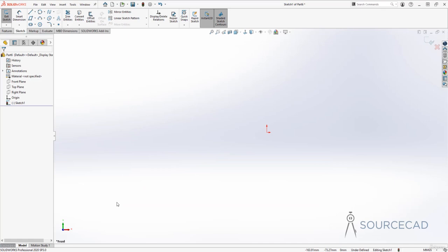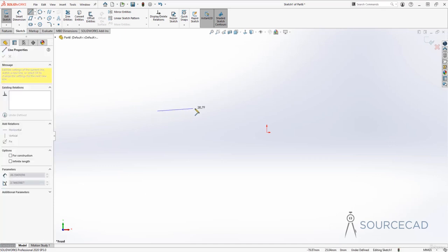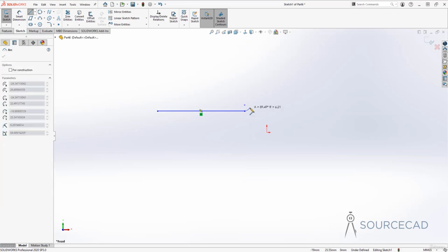Now finally, you can convert your line tool into arc very easily, kind of like this. So I'll start the line tool, I'll click at a point and I'll make a simple horizontal line. Now again, it will start the line obviously, but if you want to convert it into arc, all you need to do is go back to the same point, but don't click, just go back to this point and now move it out again. And this time what we have is an arc.